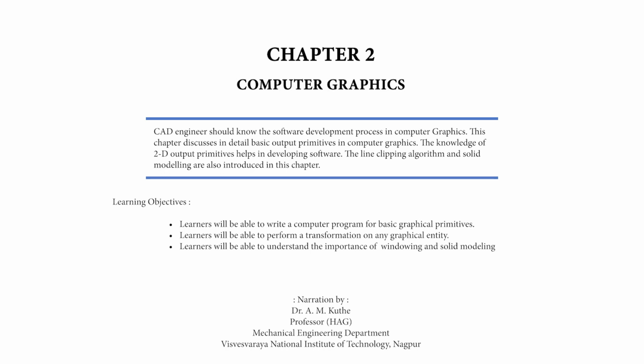Number 4. Addition or subtraction of entities is easier in solid modeling, whereas it is complicated and confusing with wireframe models. For example, a block with 6 cylindrical holes can be created by creating a block first, and then 6 cylindrical units can be easily subtracted in solid modeling.